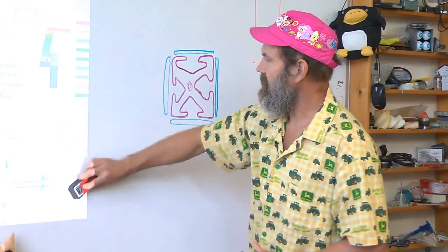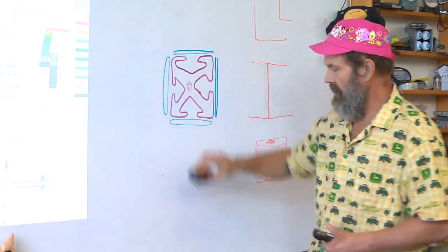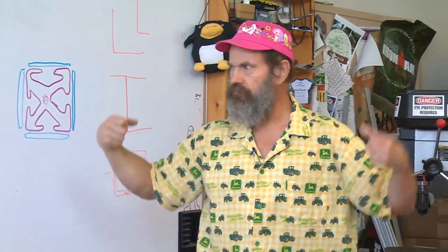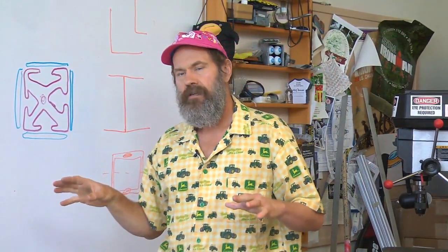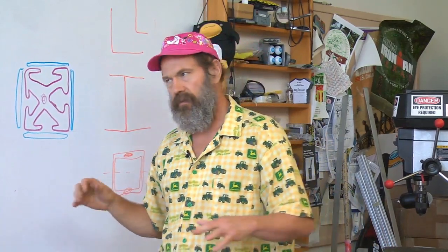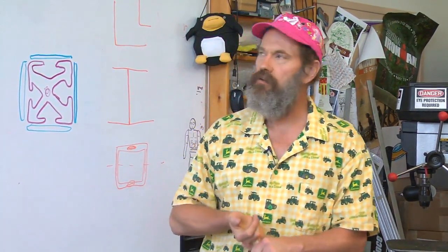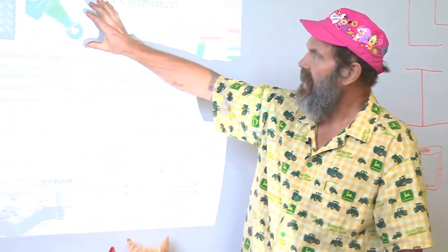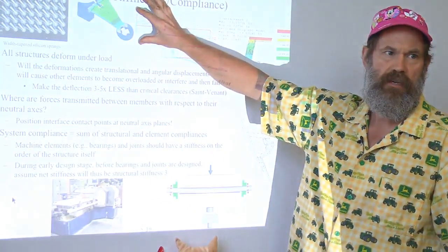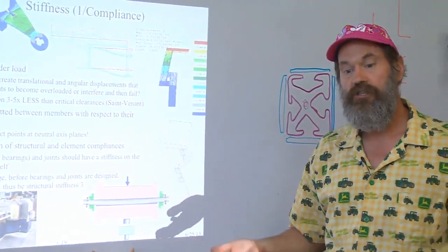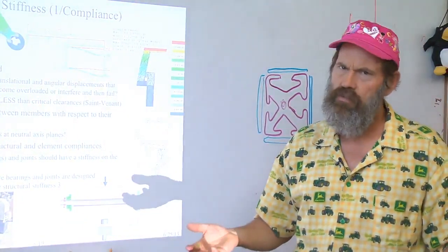Now, we've been talking about stiffness of the machine as if every machine should be infinitely rigid and stiff. There are a lot of machines that you want to have compliance built in for energy storage, for taking shock loads. You want to design your machine to have a springiness to it because, face it, in a car, if there was no suspension, it's really rough to drive.